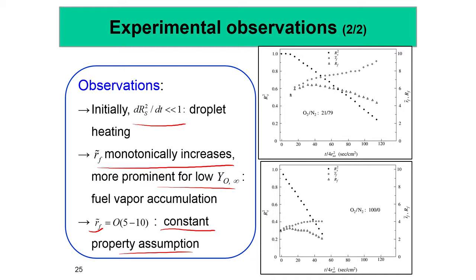So with this we close today's class, and we have covered a lot of ground. We have studied a lot about non-premix flames. We used the coupling function formulation, combining today's and previous days' classes, to explain the structure of a non-premix flame. One can obtain the burning flux, the species profiles, the temperature profiles, and most importantly we can find that the flame temperature becomes essentially the adiabatic flame temperature for a non-premix flame, for the given fuel mixture on the left hand side and air mixture on the right hand side.